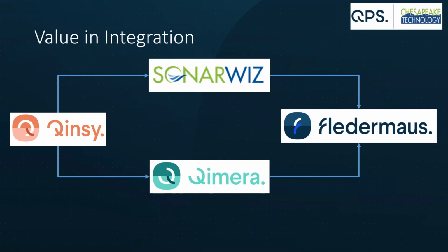Another question that came in is, can you fix the navigation spike? Yes, there's a program called ZEdit. Terrible name for a program, but inside that ZEdit you can adjust navigation, X, Y, sound velocity, if you have a spike in your sound velocity. It's a simple program to use, and it opens up the CSF file, reads that portion of the CSF file, updates that one section, and saves it back.